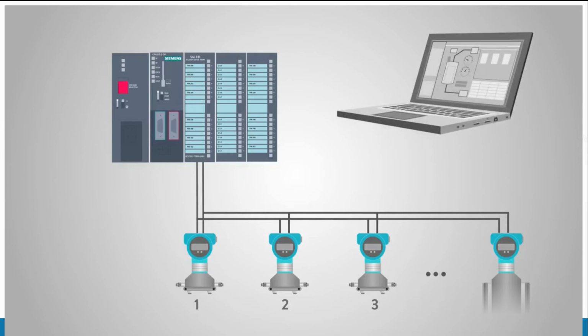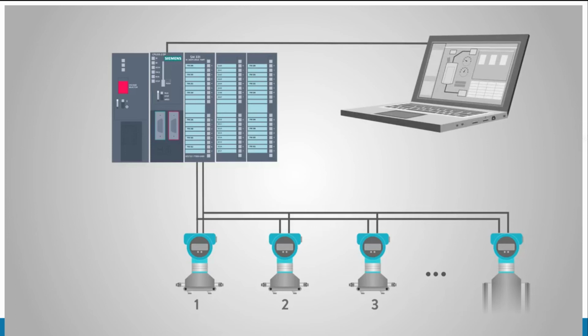The remote capability of Hart sensors is very useful and powerful. In this diagram, we see a Hart sensor connected to a PLC analog input card. We can access data in the sensor remotely using the Hart Communication Protocol from the PLC programming software. That means we do not have to be at the location of the sensor to access its data. We can configure, calibrate, and retrieve diagnostic data from a control room or other location where the Hart data is